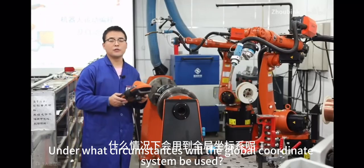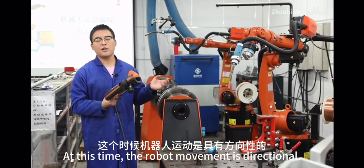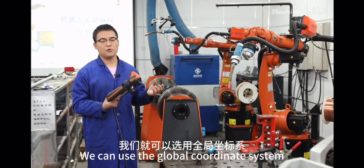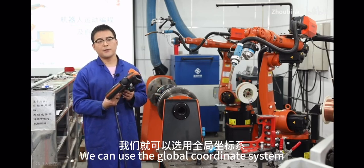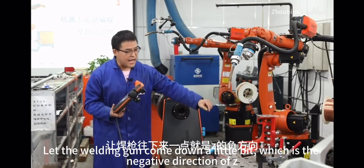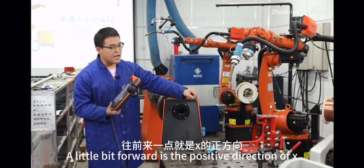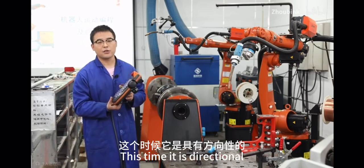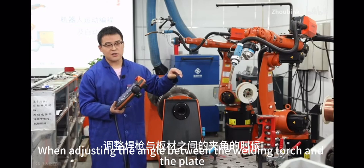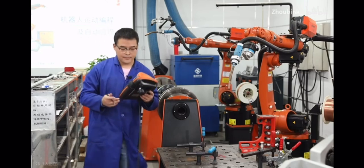Under what circumstances will the world coordinate system be used? As you can see, at this time, the robot movement is directional. So when it comes to precise positioning, we can use the world coordinate system. For example, in the welding process, come down a little bit, which is the negative direction. To the left is the negative direction. Forward is the positive direction. This time it is directional. ABC, when we weld and adjust the angle between the welding torch and the plate, is very convenient to use.